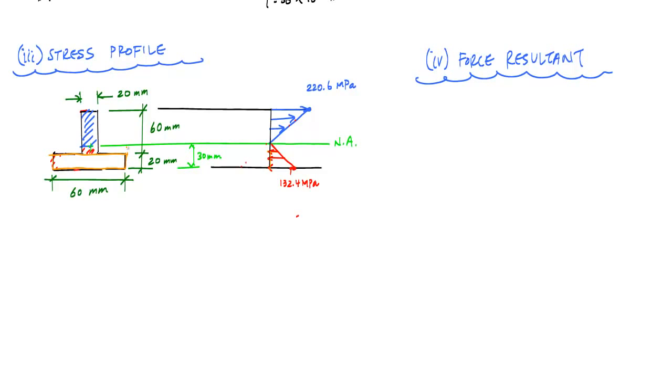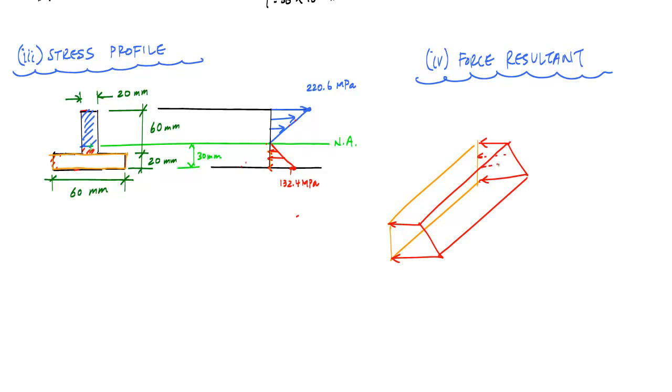And so if I could draw this in 3D, if this is my flange area, bam, like this here, my stress over that flange area is this trapezoidal volume looking thing. There would be this trapezoidal stress volume acting on the flange zone, and what we want, the force resultant, is the volume of this stress.